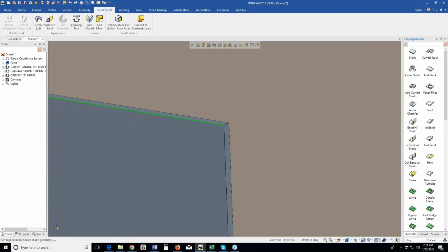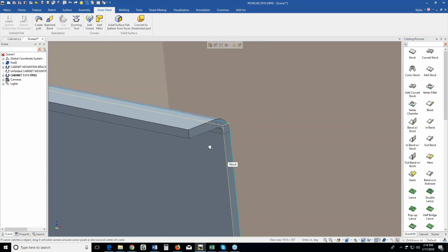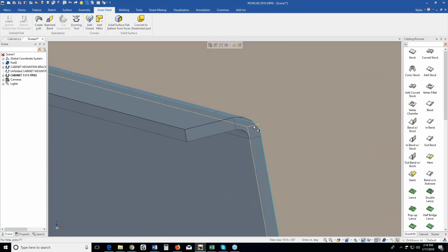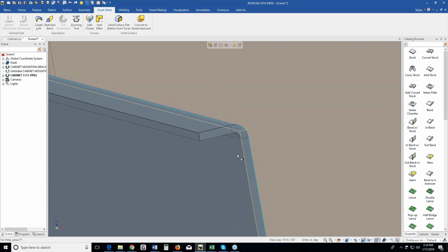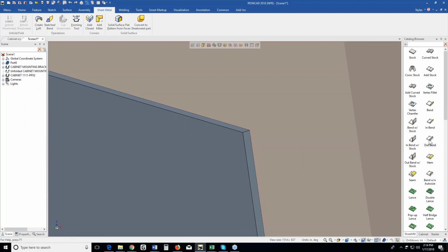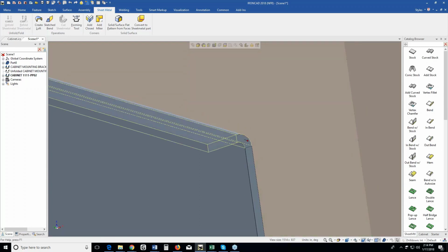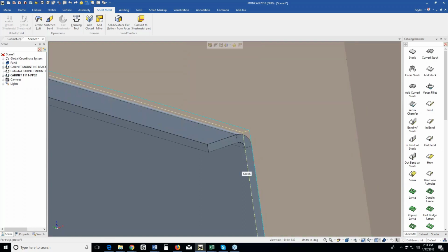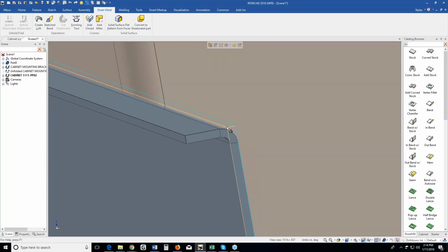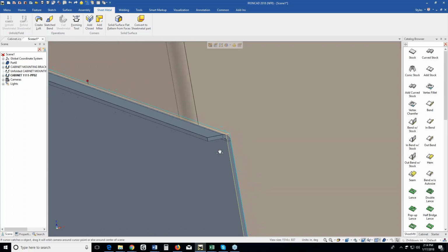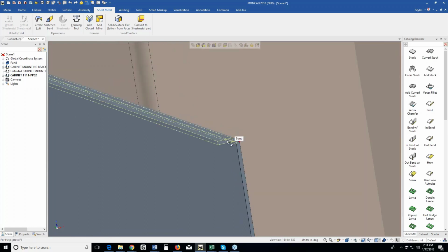If I do an inside bend, what you'll see is that the dimension of my plate is held equally to the inside of the bend that I have put on. And as I mentioned earlier, outside bend is the one that I most commonly use. And you can see by holding the outside bend, if I have an outside dimension of 36 inches, by using an outside bend, I'll maintain that. Also, what you'll see is that those same options are available with stock.